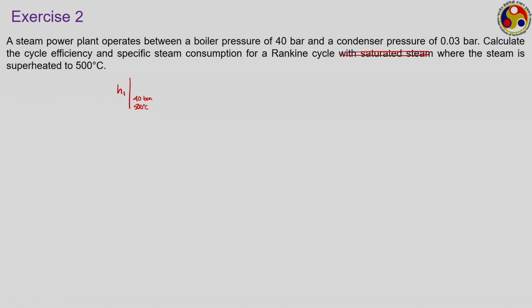So, once we go for the superheating, one of the earlier problems that I have mentioned, that we are restricted by the critical temperature limit, is no more applicable, because we are doing the phase change at a temperature lower than critical, then we are taking the vapor phase and heating up to a higher temperature, so that we can go to a much higher temperature limit.